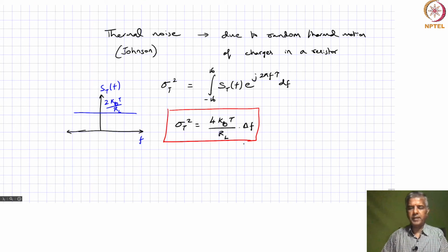When you're looking at this, you are saying, hey, it looks like the higher the resistor value, the lower my variance will be, so what I want to pick is a higher resistance value. So for example, in a transimpedance amplifier, the feedback resistor is my load resistor, and if I increase that feedback resistor, it's actually good.